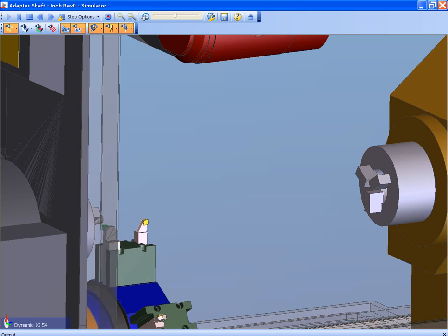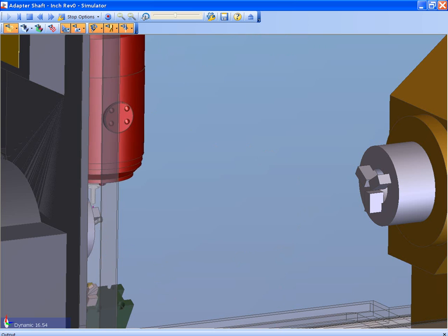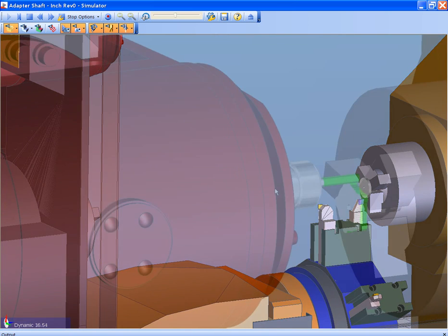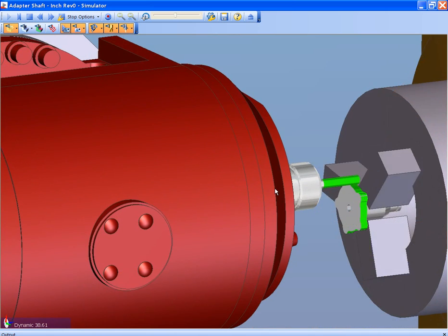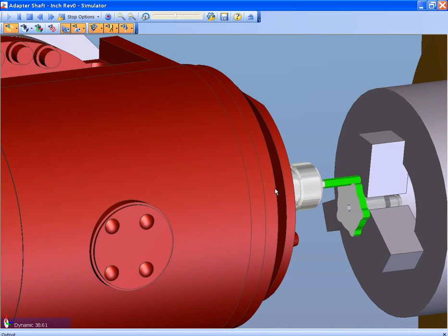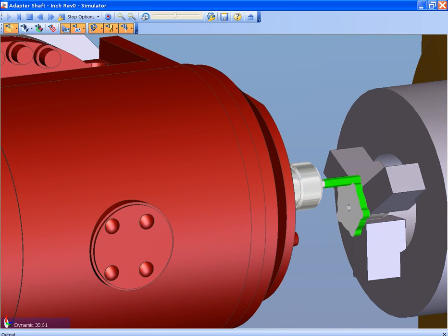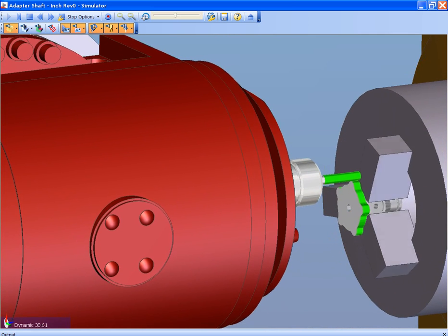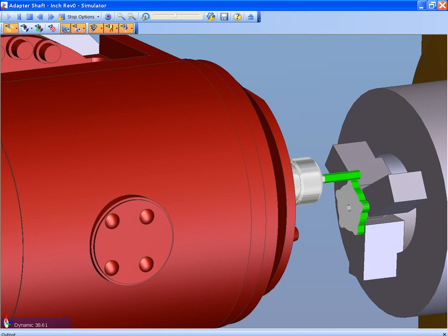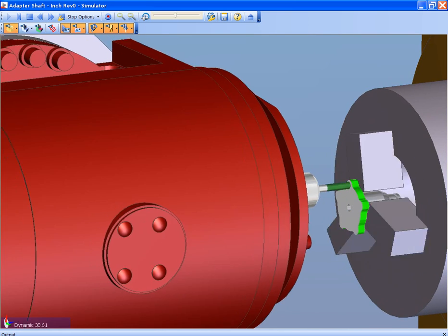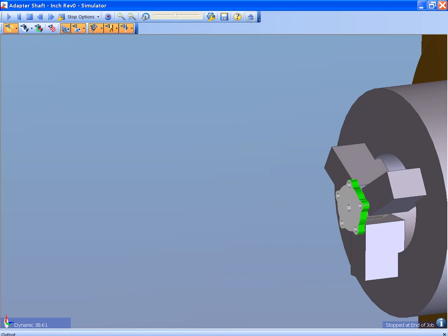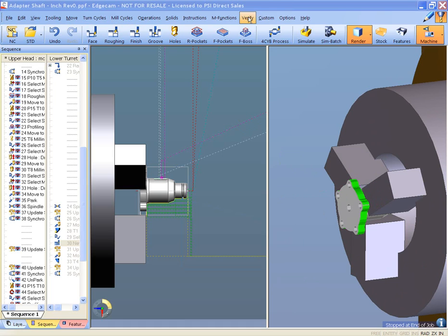The process that has driven these toolpaths was Edgecam's knowledge-based machining, called Strategy Manager. Strategy Manager allows the automation of Edgecam in a fast and friendly atmosphere, most like a flowchart application. The manufacturing commands are easily captured from Edgecam by a copy and paste method. Then the decisions are added as required based on the triggers that define your process.